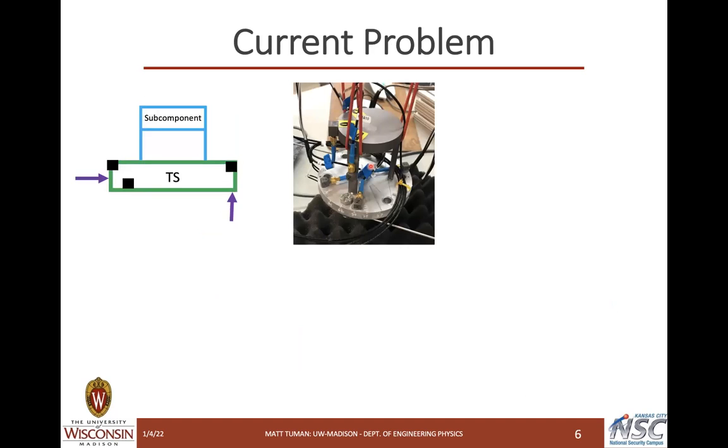So we have our subcomponent, the stool, and the plate, which is our transmission simulator. We then use control hardware and a multi-input, multi-output, otherwise known as MIMO, test setup with 6 small shakers to recreate the environment profiles on the plate. It is important to note that the control software is only controlling the response of the plate. The stool is not controlled.